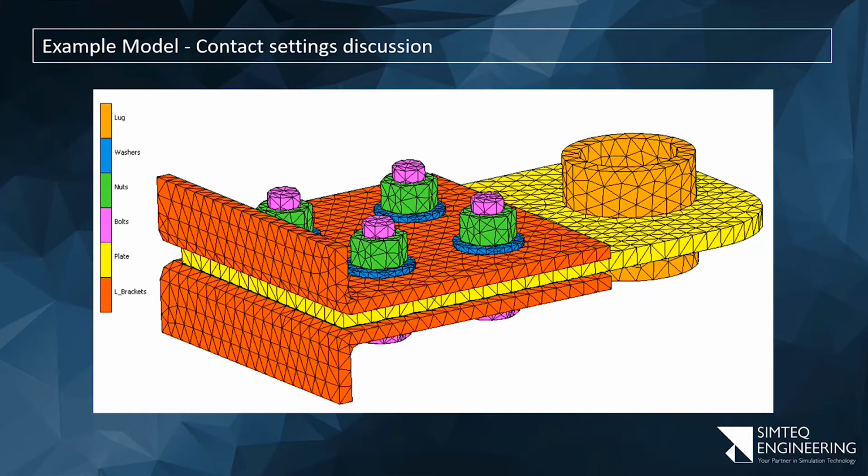Okay, so ideally project stress-free to start off with, but then also the interference fit that'll ramp up to then cause a stress in that location. I'll also need friction, because without friction, this thing will simply slide out. But that's it, not much else. I don't need to model that, use that delayed slide off, since it's touching contact also. None of the other separation stuff is important.